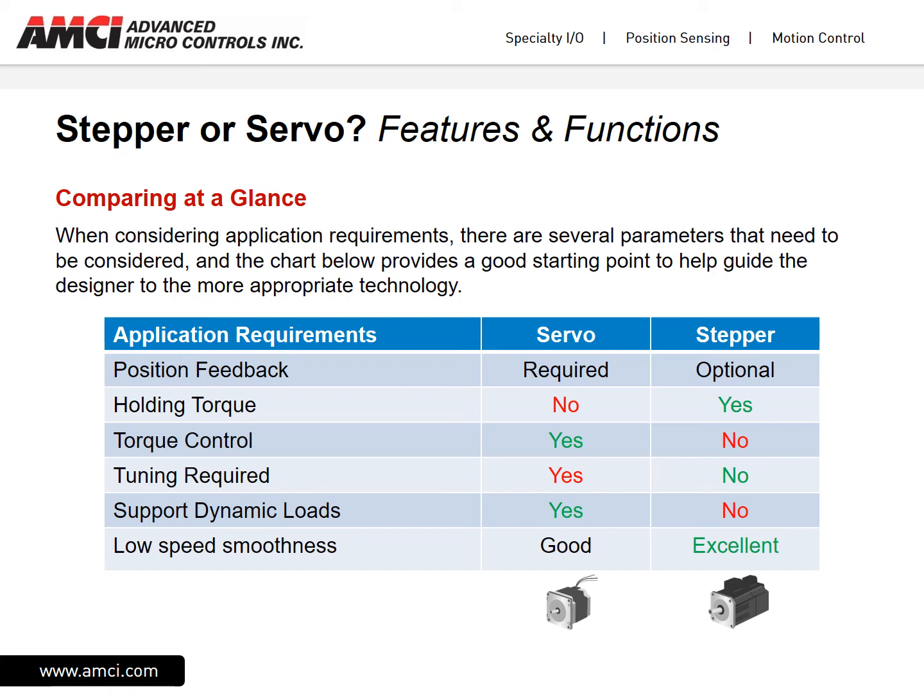Do we want to simplify control? If we do, the stepper's open loop system is a much simpler operation than a servo. With a servo, our control loop needs to be tuned to maximize operational efficiency.